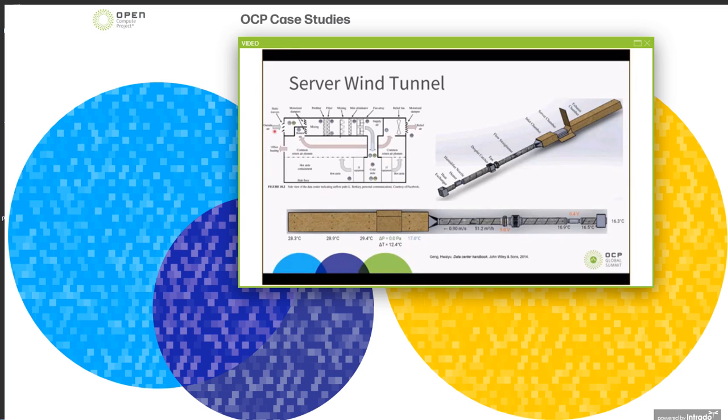In the beginning here we have the cold outside air, which is cold because we're in northern Sweden in Lulea. In the wind tunnel we have a heat exchanger to cool the air. It is then mixed with the return air coming from the IT equipment. While we do not have mixing from the return air occurring, we have a heater to simulate this process. After that, the air is filtered, misted, and passes through a mist eliminator before the fans push the cold air into the cold aisle, which is also occurring here in the wind tunnel.